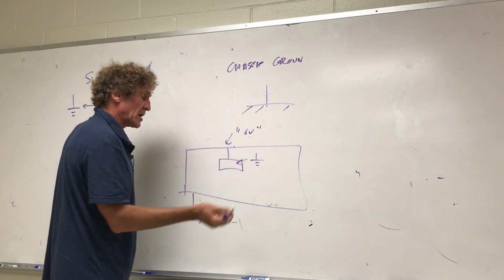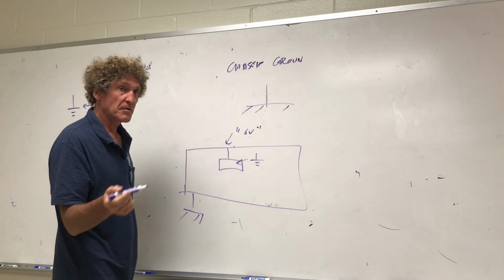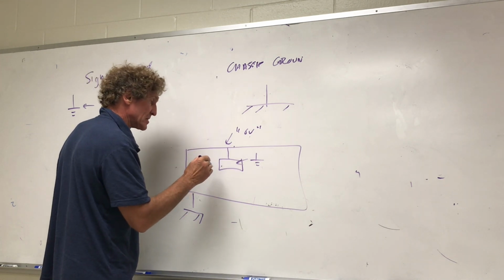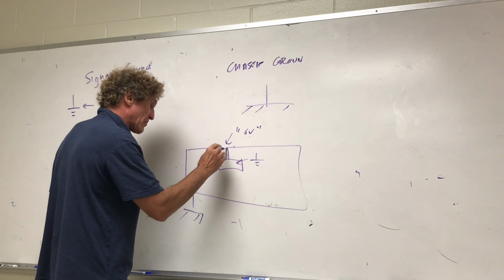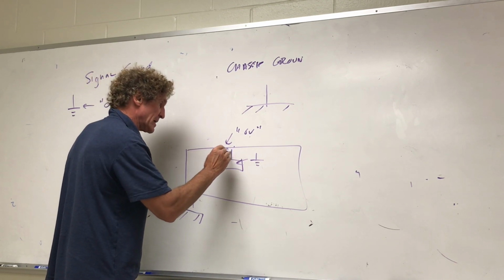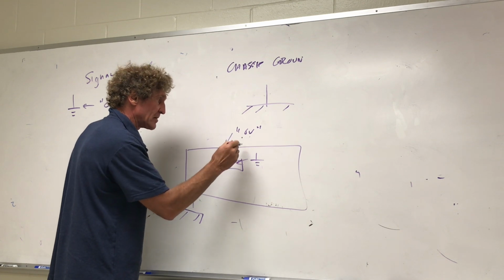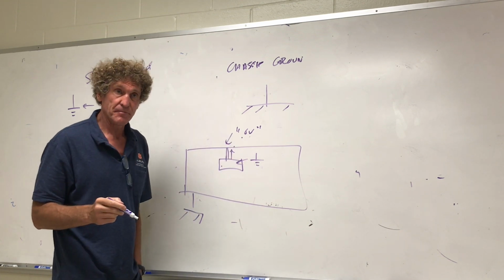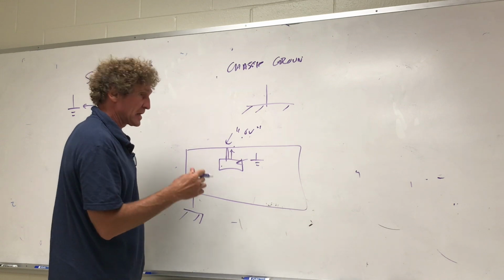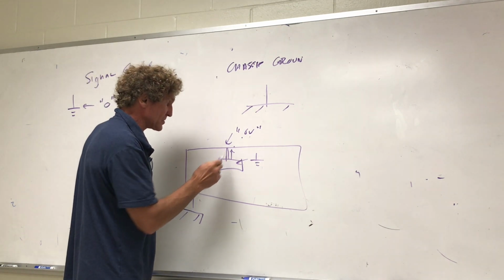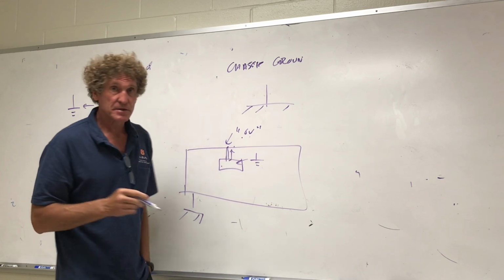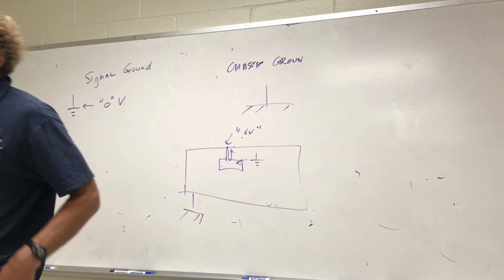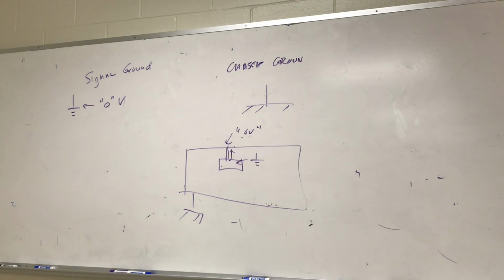There are power supplies, there are a whole bunch of other things that complicate this. There'll be positive leads, all this stuff going into each thing. But this wire right here will have current in it if the signal ground and the chassis ground aren't the same. And it can be significant at high frequencies because there will also be an inductance there where you'll get millivolts of difference, and actually between the chassis and signal ground, sometimes even more, maybe tens of millivolts at higher frequencies.